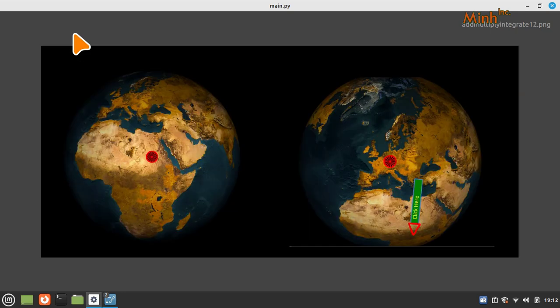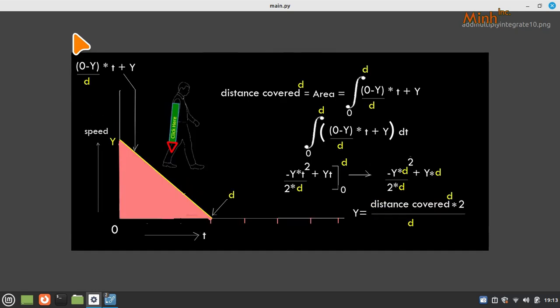So the idea is it should take constant time. Okay, if it is moving 170 degrees, or it is moving 720 degrees, or it is moving 340 degrees, it would take the same time. If it is taking the same time, the distance is different, and then certainly it has to start with a different speed and then slowly it would reduce. So that we'll see in the lab session, how it actually looks. But this is the concept that we'll follow.